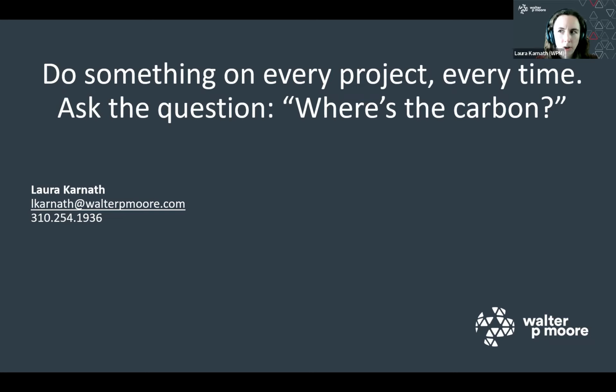Yeah, and it's also important to note that a reduction in embodied carbon doesn't necessarily mean an increase in operational carbon. That's why we're trying to use functionally equivalent systems, like the same amount of insulation but maybe a different type, versus saying, oh, it's okay if we reduce the insulation and increase the operational emissions.